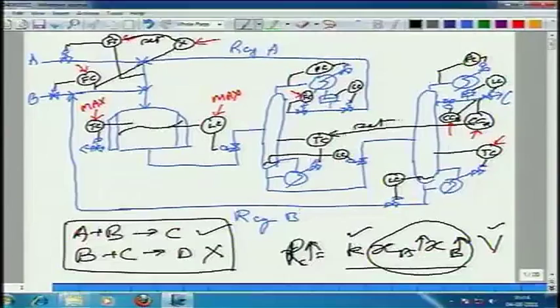Well, why did I say this? The point is that depending on the chemistry of the process, it is fundamentally tied to how you set these set points. There is no control theory here. Your reaction scheme, whether the primary side reaction is a series reaction or a parallel reaction, etc., determines how the hell you operate the process.